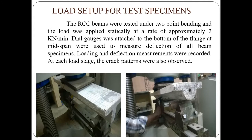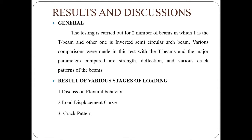Load setup for test specimen. After casting and 20 days curing, the specimens are completely dried and placed in 2-point loading. Dial gauges attached to the bottom of the flange at midspan were used to measure deflection of all beam specimens. Loading and deflection measurements were recorded at each load stage. The crack patterns were also observed.